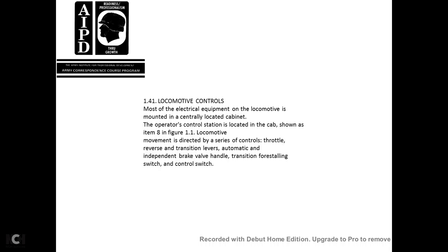140. Pneumatic control switch. When the emergency brakes are applied under similar conditions, the engine power is reduced by pneumatic control switches. The switch opens when the brake pipe pressure is reduced, and the opening of the switch stops the engine, cuts off the fuel, and turns on the indication lights. The throttle is returned to idle, and the brake pipe pressure is restored, with the switch resetting itself.